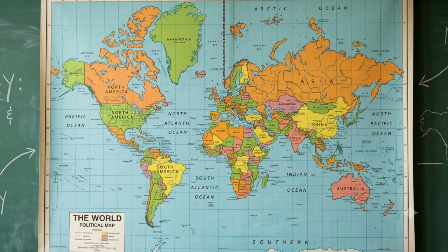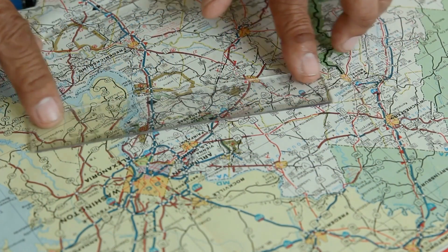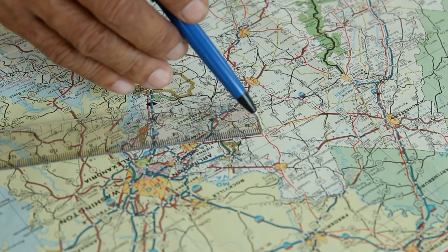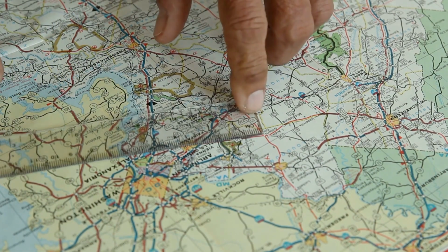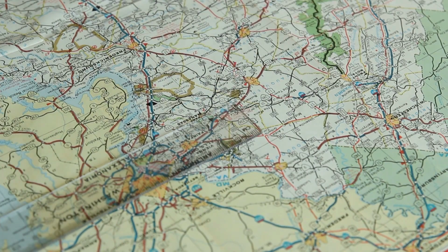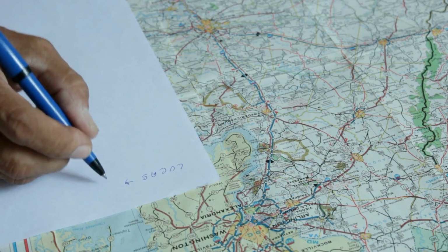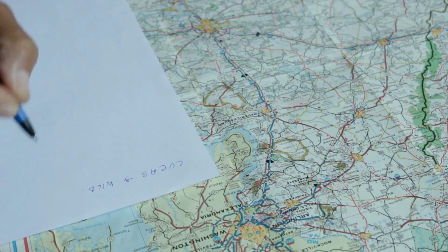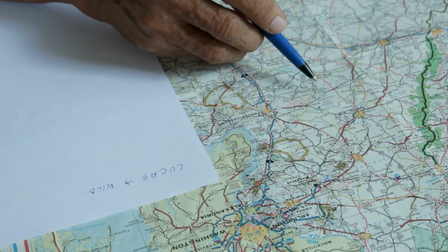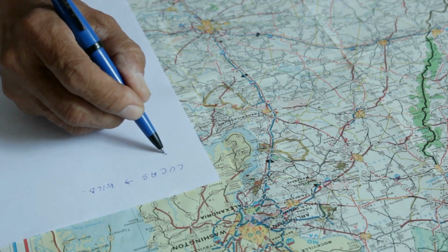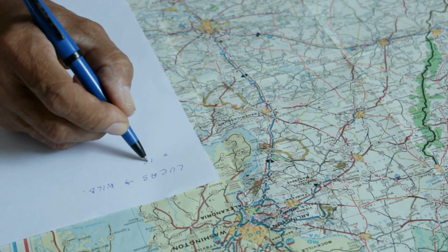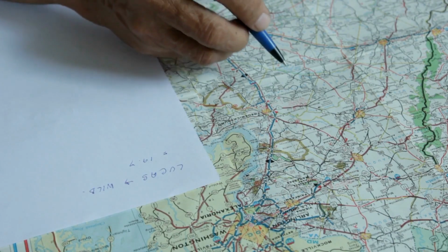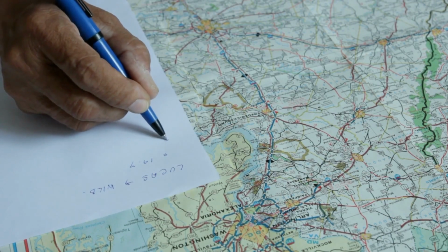14 times larger. The study sources provide a startling mathematical example of this. If you measure a long-distance route on a Mercator projection using the software's flat measure tool, you might get a result of 3,124 miles. But if you take that exact same real-world space and measure it on an Albers equal area projection, which utilizes a conic developable surface to accurately preserve scale over that region, the true measurement is over 24,000 miles. It's just staggering. Because a projected coordinate system isn't using decimal degrees like a globe, it's measuring flat space in actual meters and feet. If the mathematical flattening stretches the landmass, your digital ruler stretches right along with it.